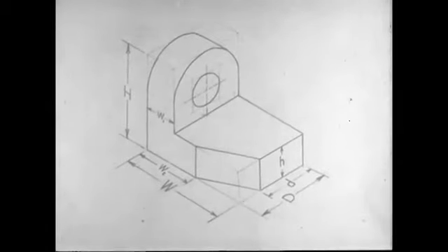The curved surface and the hole have one center. Since you know its height, measure this height from the bottom line of the side view and use it to locate the center for the hole and the curved edge midway between the vertical lines of the side view. Draw horizontal and vertical center lines through the center on the side view. Project the horizontal center line to the front view and draw the center line for the hole on the front view. Draw the center line on the top view to locate the hole.